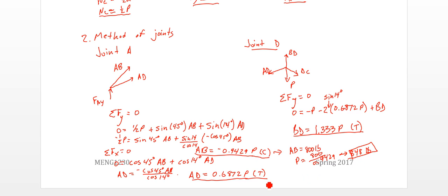And then for our tension case, it's a little more tricky. We have two values of tension. If we pick this one, it's a smaller value of P. So if we set that equal to 1500, we'll find something much greater than 1500 here, versus if we set this one equal to 1500, we're going to find P is something less than 1500 since we have a multiplier greater than 1. So this is our limiting case here.